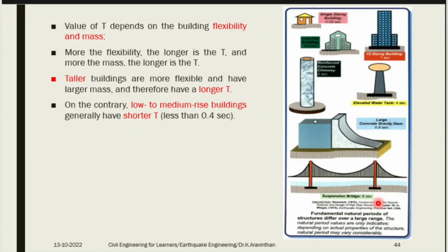Okay, suppose your earthquake is coming with a time period of 20 seconds. Will each structure get collapsed? Now imagine an earthquake of 20 seconds time period. Is any structure going to collapse here? Identify all the time periods of the structures. One storey has 0.05 second, and a multi-storey structure has 1 second. No way do you have 20 seconds of time period. So if an earthquake of time period 20 seconds arrives, no structure will get damaged.